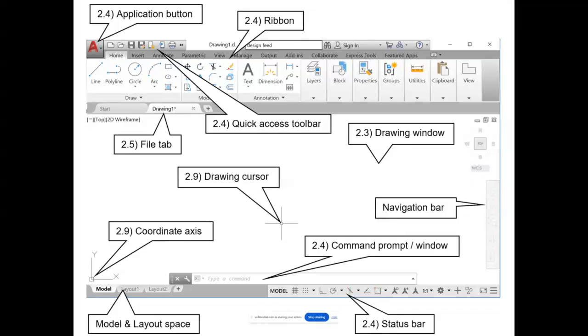You still have a command prompt, and I'm going to show you how to dock that guy and make it bigger because the command prompt's really important. AutoCAD is probably the last man standing or close to it on software that has a command line that you can see what the program's doing. What am I doing? Where am I at? What am I looking for? It's only going to do what you tell it to do, right? Most of the time. We don't have AI in that one yet. Or at least I don't think so yet.